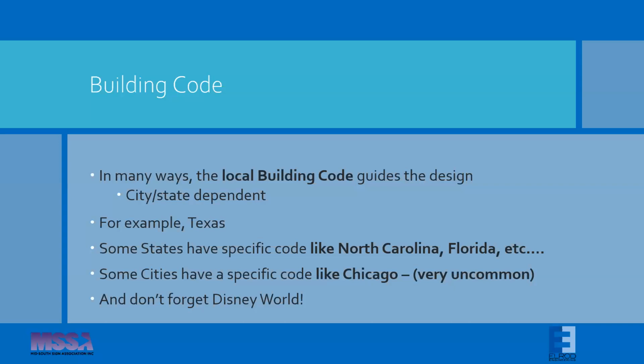Surprisingly, cities often do not view codes as backwardly compatible. For example, you would think that if you designed a sign to the 2021 version of the building code, it would be applicable everywhere. But if the city has adopted a 2015 version, they will not accept calculations or drawings that are done per the 2021 building code and identified as such. This information about the building code is particularly important for your clients who may have a pre-designed family of signs that are installed across a large region or even nationally.